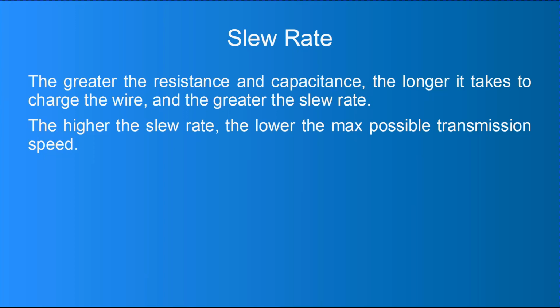So typically with a long haul, like a 1,000 meter RS485, you end up having to drop your transmission speeds back because it takes longer to charge the wires up.